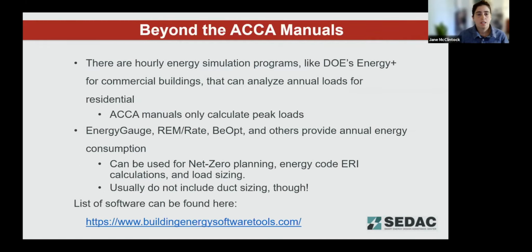So those are the three ACCA manuals, which together are able to design the full HVAC system. But beyond the ACCA manuals, there are hourly energy simulation programs, such as the DOE's EnergyPlus for commercial buildings, that can analyze annual loads for residential.